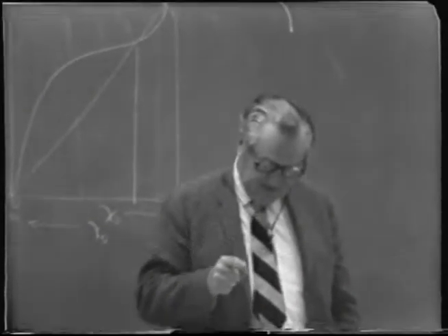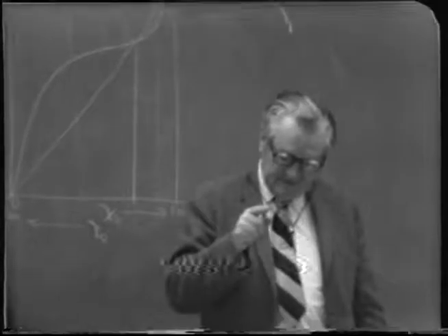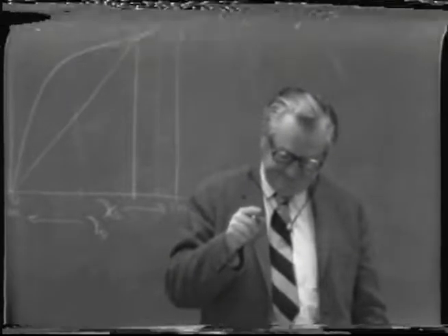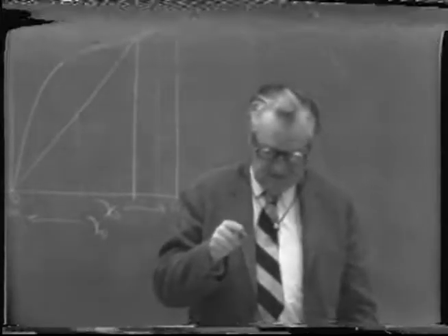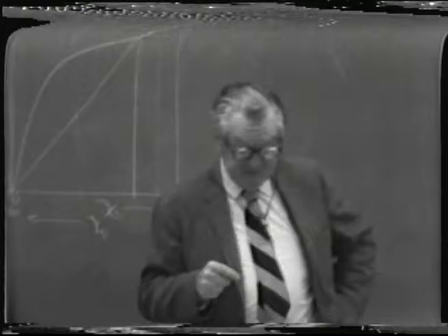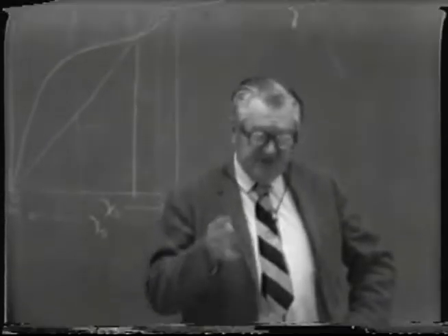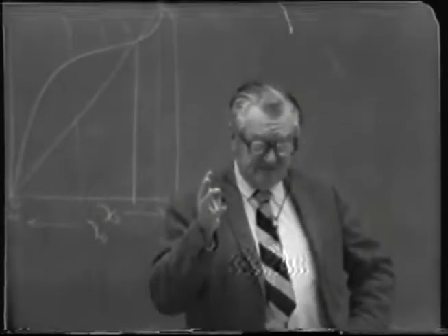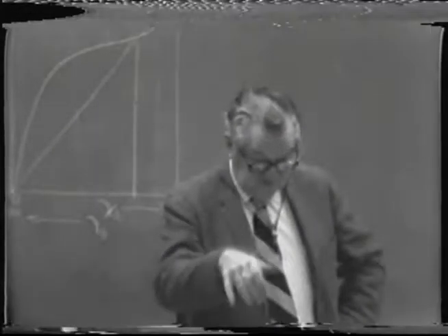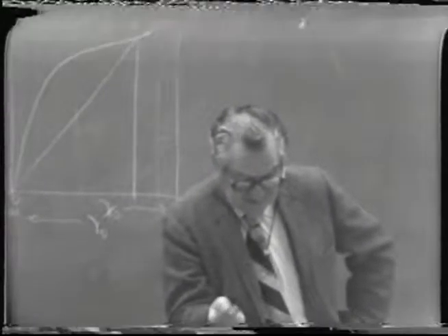I might say that the main consideration here in the allowable plate spacing for a particular vapor velocity, or saying it the other way, the allowable vapor velocity for a particular chosen plate spacing, is really based on the concept of plate efficiency.